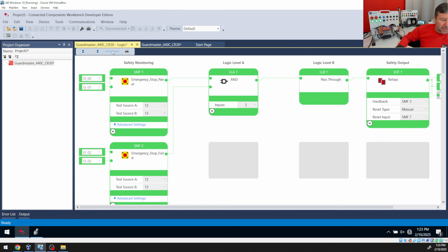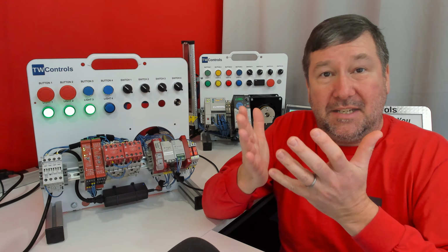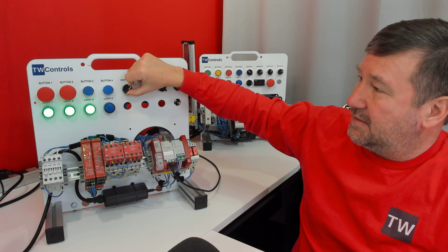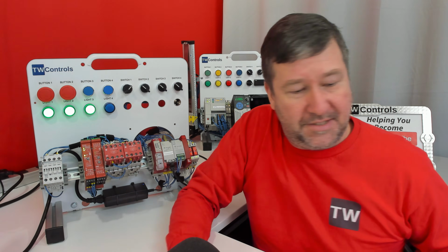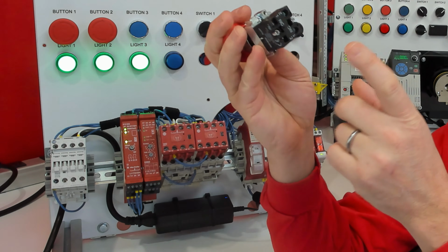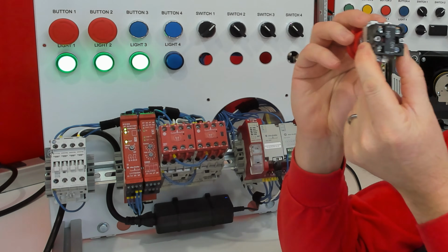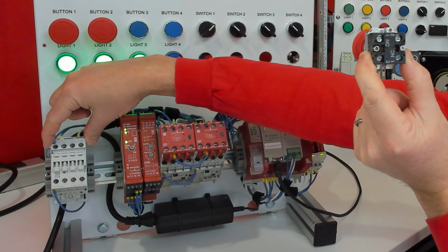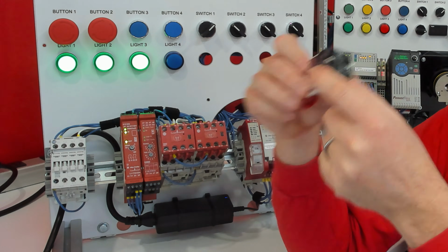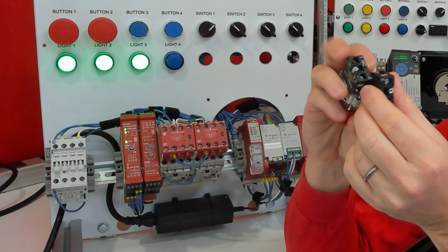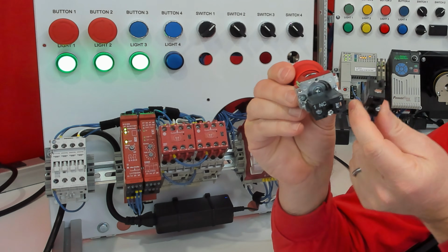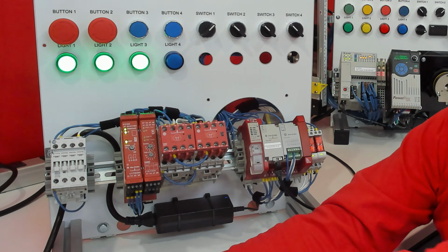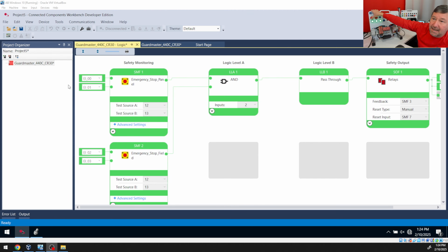All right, now let's talk about troubleshooting some of those same scenarios that we did with our safety system. If you recall, switch 1 is going to break one of the contacts on our emergency stop. On the back of our safety relay, it has 2 sets of contacts for these redundant setups, and we had a single contact on our older MCR setup. What switch 1 does is pretty much simulate this contact getting broken off or being stuck, so that we only have the one contact actually operating. And I'm going to press my e-stop.